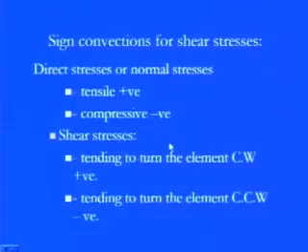As we discussed, there are sign conventions for the shear stresses. For the normal stress components, we already discussed the sign convention. Just to remind you again: if tensile forces are there, if pulling is there, we always consider the stress positive. If compressive stresses are there, we always consider the negative sign convention for the compressive force as well as the compressive stresses.